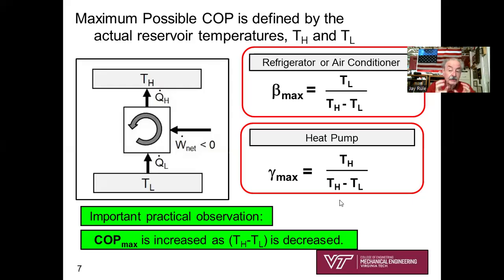And when you run through the calculations for either an ideal vapor compression refrigeration cycle or an actual one, those coefficients of performance are going to be much, much less than the Carnot cycle. I find that to be an extremely interesting comparison between maximum possible and observed coefficient of performance for either the ideal or the actual vapor compression refrigeration cycle.